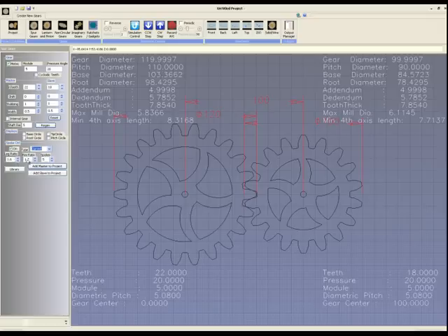Along with that is leg ratio, rim ratio, and the number of spokes. These are not standard specifications for gears. Normally you would specify your spokes by how thick you want your rim to be and so on. But we've tried as hard as we can to make Gearotic as easy to use as possible. So rather than enter a situation where a person changes the number of teeth or the module of a gear and then is left with spokes which are far too small for that gear, we've gone with percentages in order to create a spoke which parametrically follows the size of the gear being created. This isn't optimal for a lot of users though, and as I say, the new spoking manager to come at some time in the future will address those concerns.